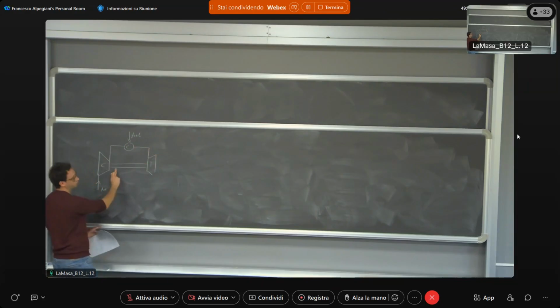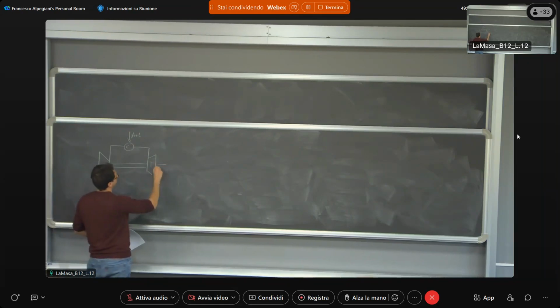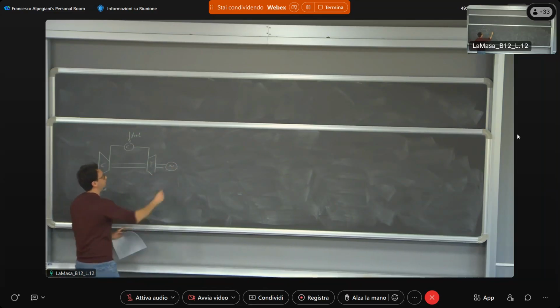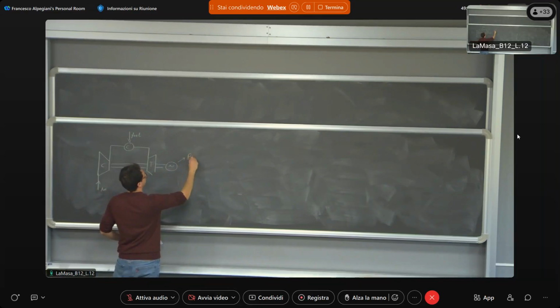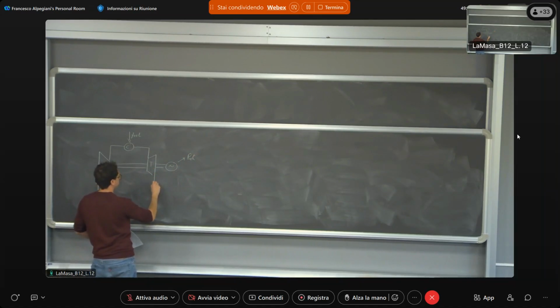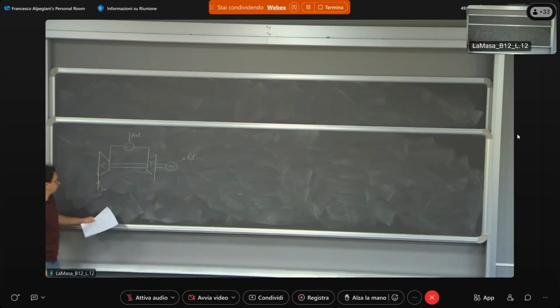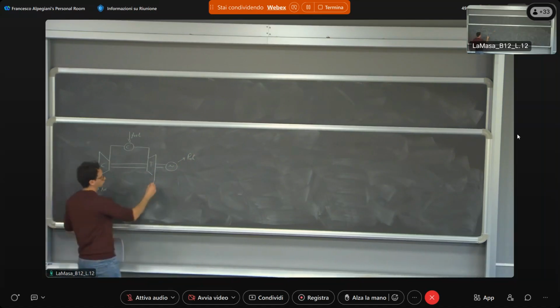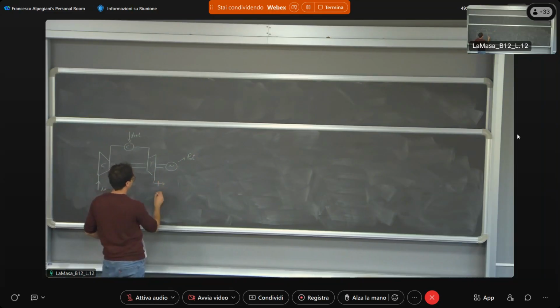This is a shaft, so the turbine power is used to drive the compressor, and then it is linked to an alternator, and so from here we extract the electric power. After the gas turbine, the expanded flue gases, with a pressure in this case equal to the ambient pressure, go to the ambient. So here we have the expanded flue gases.